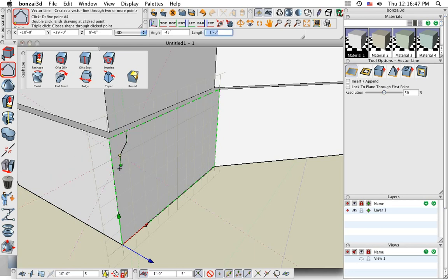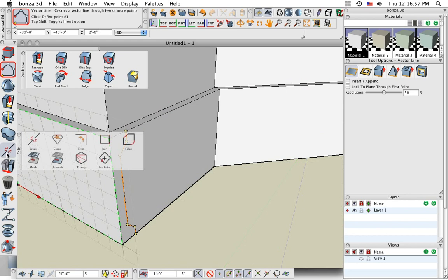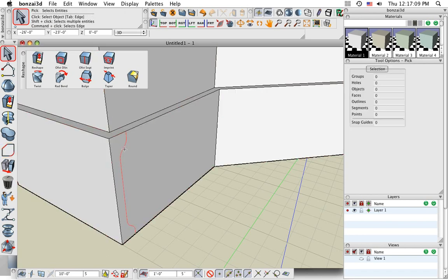And I can use the vector line tool and switch over to the arc tool and spline tool and just sort of mix and match those drawing tools in any combination that I want. And there we go. Now there's a 2D shape. As soon as I create it, I can move those controls to modify that shape if I want. There's some line editing tools. So I can join, trim, and close lines if I want. Maybe put a fillet radius on there to round those corners that are there. Okay. And once we got that shape, that is a separate object.